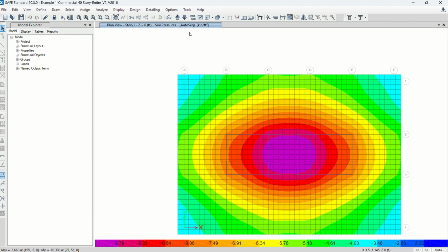This is the soil bearing stress. If you remember a spread footing, we assume the footing works like a rigid body, so we use a uniform load distribution based upon your column load. But since we are dealing with a huge mat, we need to use continuous springs.